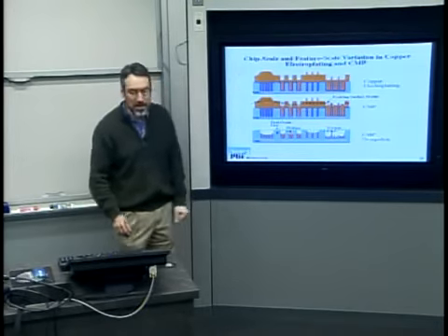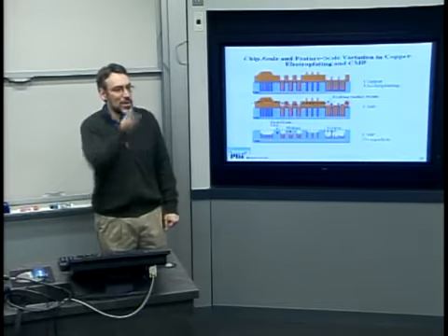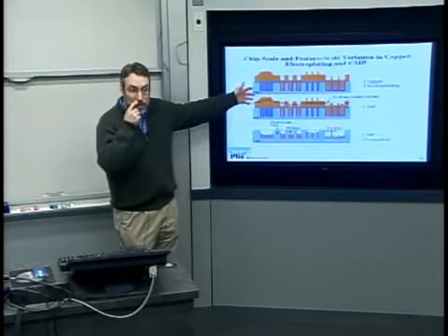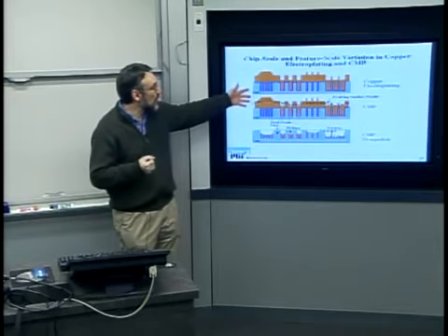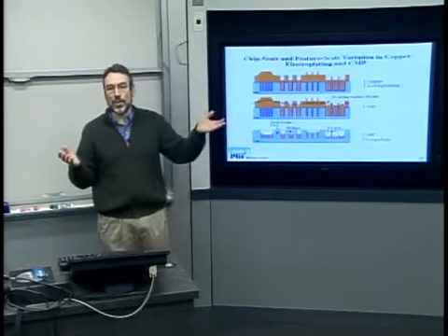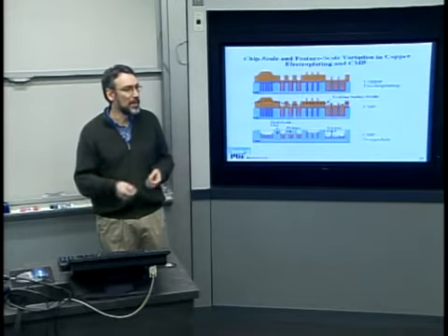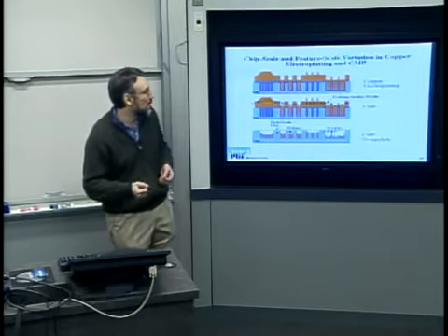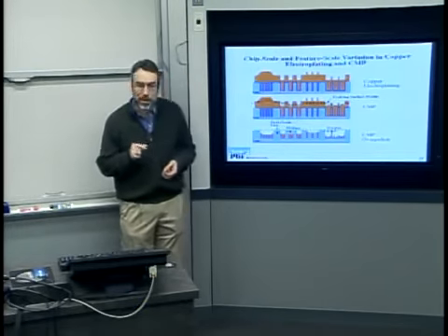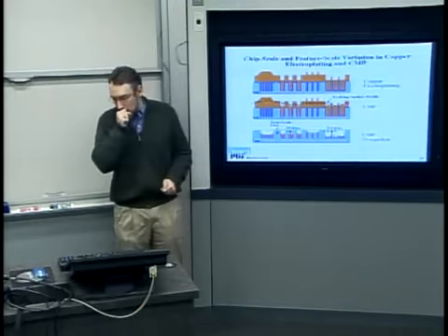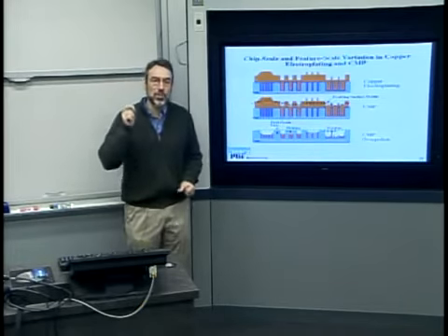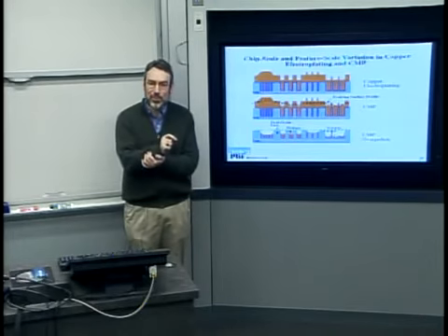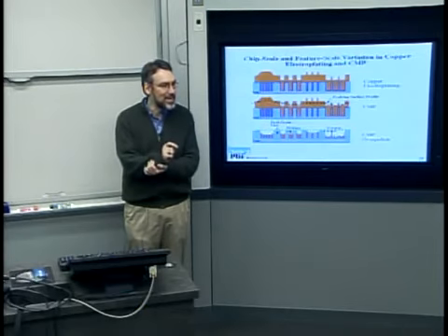There's 2 sequences that I didn't talk about in the earlier flow because it's a 10-year-old process. Modern integrated circuits, especially for microprocessor logic and now even memory, are using copper interconnect. Copper conducts better than aluminum. You get speed improvements, you get reliability improvements. It's a big drive to move to copper. But it's a little bit more complicated of a process. The basic process is different than in aluminum because we do not have an effective plasma etch process for the selective removal of copper. It's just a bad process in that way.